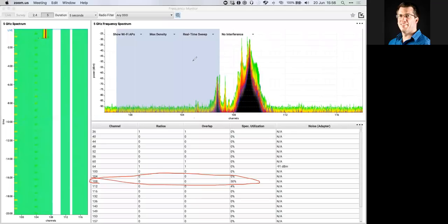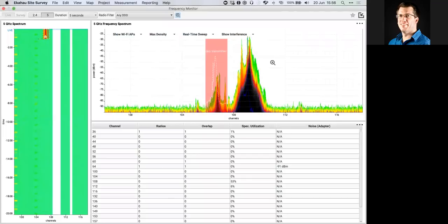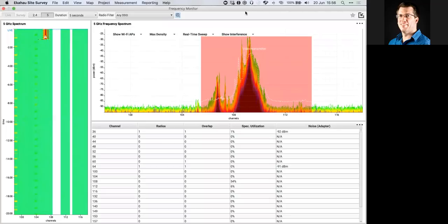So what I had before is the interferer detection. Let me just turn that back on, and it's come up as a video transmitter. So we're basically enabling it, making it easier for troubleshooting with the Sidekick while you're out in the field. So you can go, okay, I've got something weird happening, which is kicking my Wi-Fi clients off the channel. Maybe my access point or wireless controller can't tell me exactly what it is, but we can see right here it's a video transmitter, or maybe you might have a 2.4 or 5 gigahertz motion detector. 5 gigahertz motion detectors is what I see quite commonly, definitely in warehouse surveys where they'll pop up.